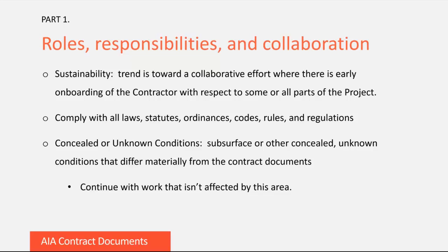A contractor is expected to comply with all laws, statutes, ordinances, rules, and regulations. These could be noise ordinances or special traffic routes for concrete trucks during large pours, especially if they coincide with rush hour traffic. And many jurisdictions regulate transportation of hazardous materials. So trucks may be required to have covers and or apply a spray to prevent material from flying out or to minimize odors.